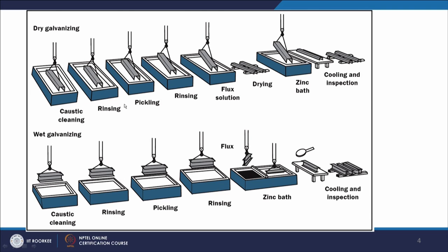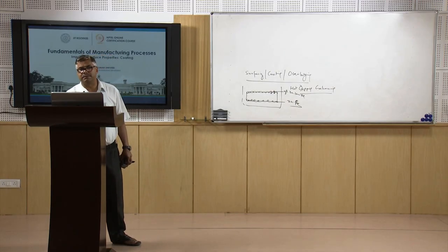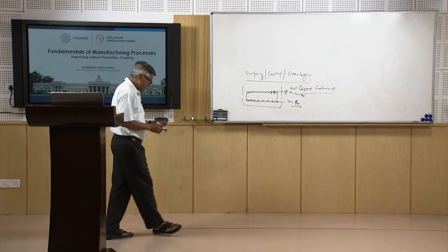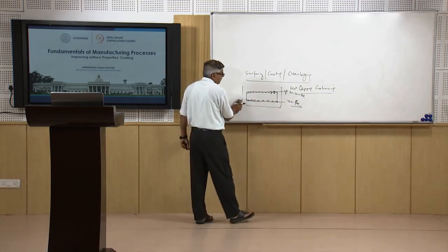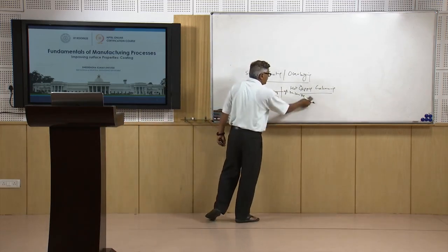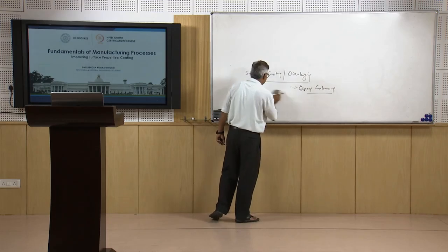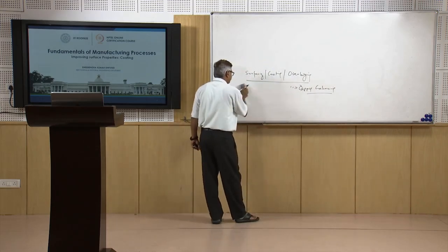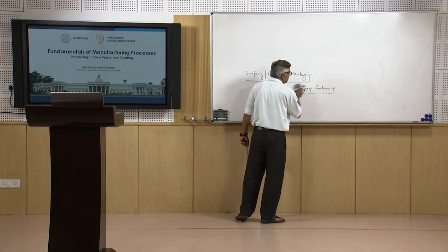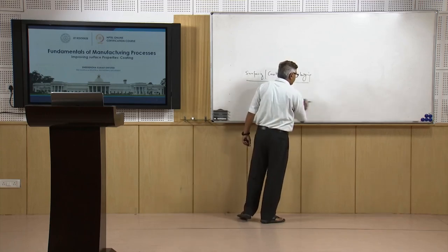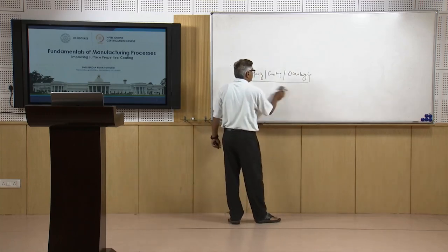In any case, proper cleaning using mechanical and chemical methods helps to have proper galvanizing of the components to be modified. So this is where the zinc layer is applied using the hot dip galvanizing process. Primarily it is used for improved corrosion resistance.